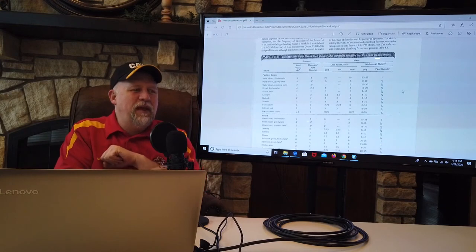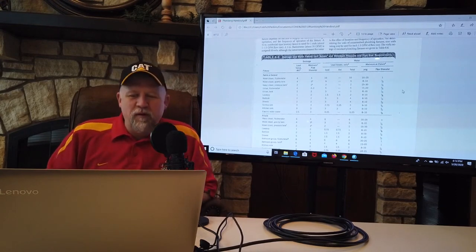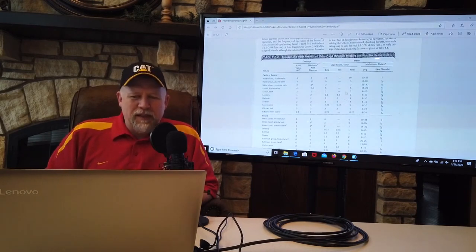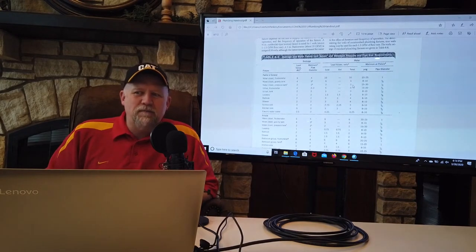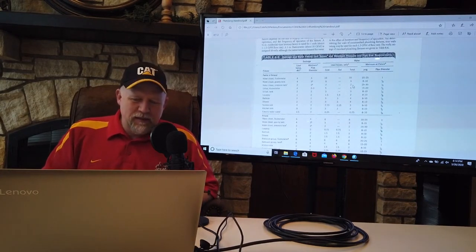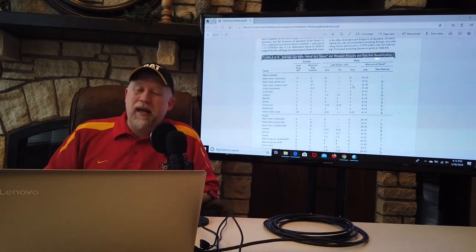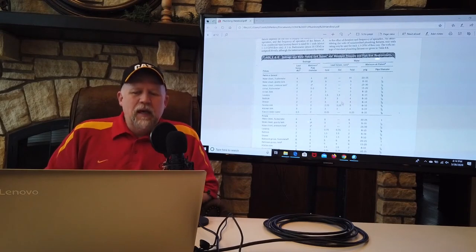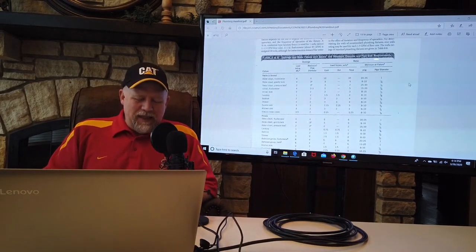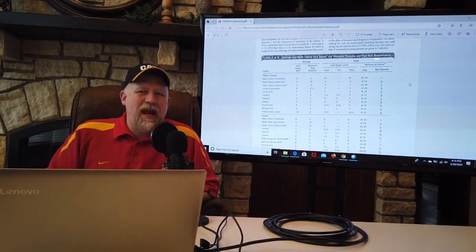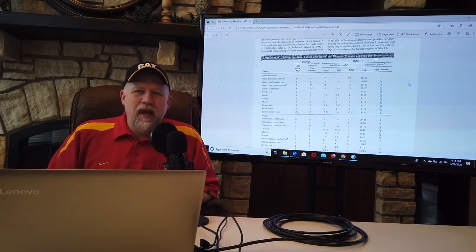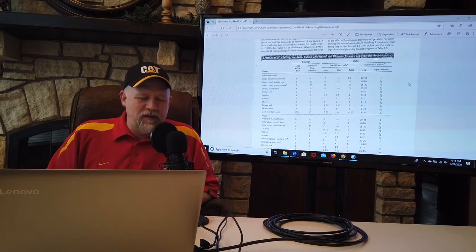This is not the type of thing they're going to calculate in fluid flow or heat and mass transfer. A drainage fixture unit and a water supply fixture unit are magical, mythical, nonsensical units that we use to size pipe in plumbing systems. They're not real units. What they do is allow us to take a time-weighted average of water consumption in a building and use that to size our sanitary sewer main and our domestic water main.